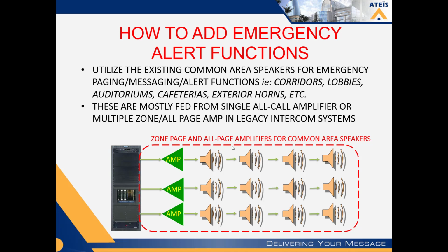It is exactly the same in any educational facility. You do not need to use the speakers within the classroom and the instructional space for the emergency alert. Now, you can always have the audio for the alert going through the intercom system and going out to all the classroom speakers, but they will not be supervised. They won't be listed as such.